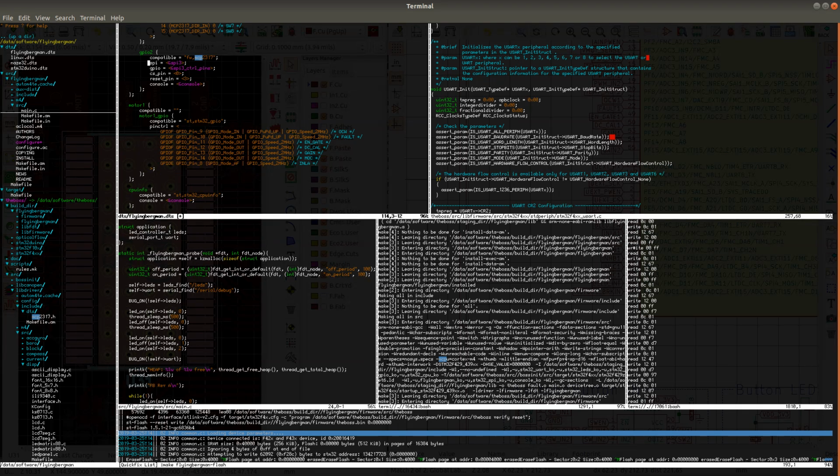Yeah, and we don't need to set mode AF is only for STM32 103. So this will be directly set to AF TIM1.